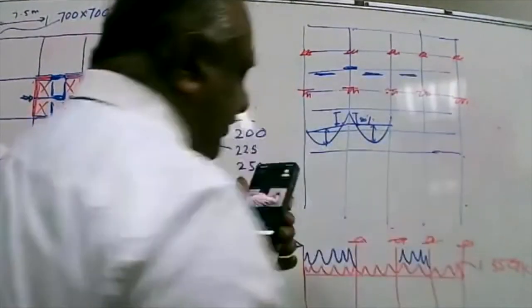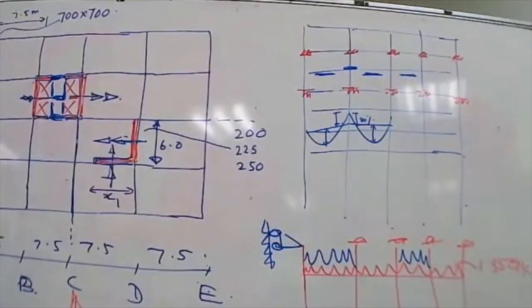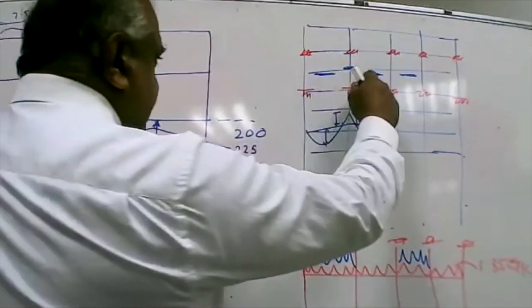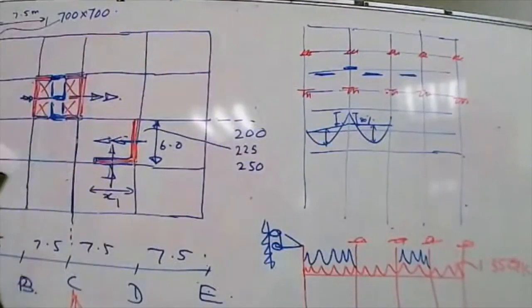So when you're calculating the reinforcement, will you provide exactly the calculated answer, or a little more reinforcement in the span sections? I would always provide a little more reinforcement in the span sections, because nothing can go wrong when you provide a little extra reinforcement there.